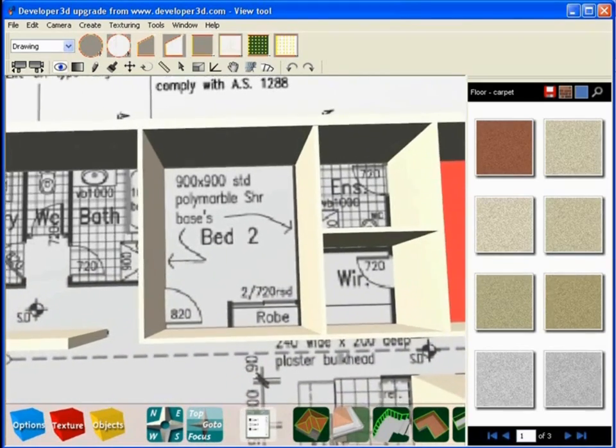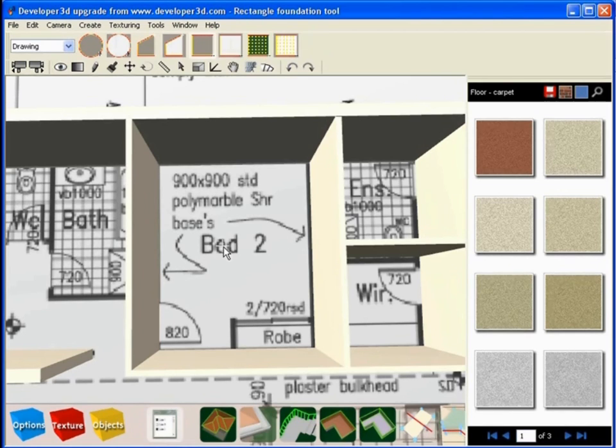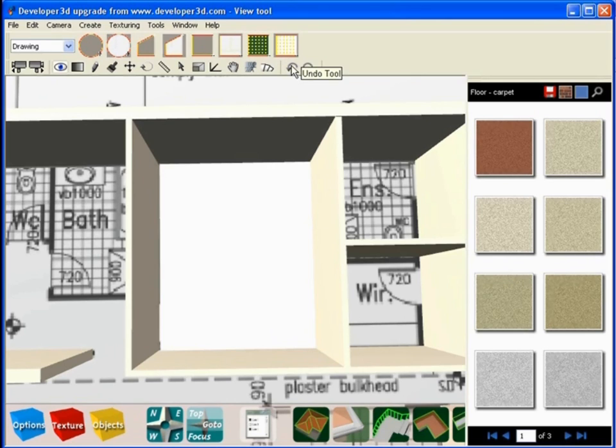It's a very simple mistake to make, so we have some assistance built into the software that works like this. You select the foundation tool, hold the shift button down, and click on the surface that you wish the foundation to be created on. You can see a red cross appears that marks very visually the surface on which the software is going to create that foundation for you. Then you let the shift button go, and you can get right into the corner here. We don't have to worry now because we've got our nominated surface, and we can create a very accurate floor for this space.